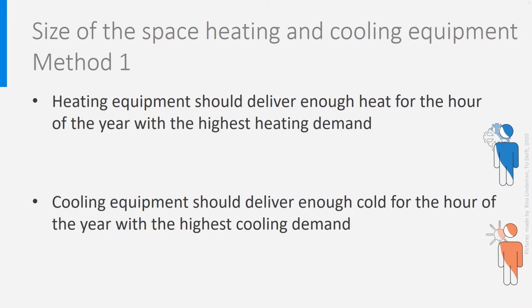How to choose the right size of the space heating and cooling equipment? We will look at two different methods. The next 5 slides are about the first method. Basically, the heating equipment should deliver enough heat for the hour of the year with the highest heating demand, while the cooling equipment should deliver enough cold for the hour of the year with the highest cooling demand.